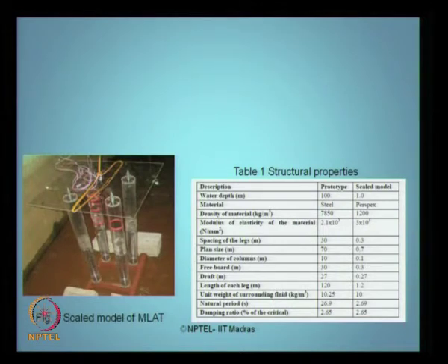Of course, you must understand the structural properties of the system, because that is important for how the tuning was done. The attempt was made for a 1:100 scale, because the prototype is about 100 meter water depth, but the scaled model was tested in 1 meter water depth. So, 1:100 scale has been attempted.